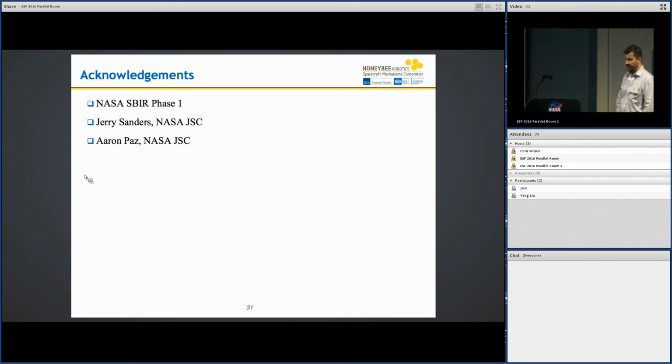Yes, probably yes. The reason why soil is cohesive, the soil that you've seen, is because the particles are really jagged, and actually lunar soil, the old one, has 50% agglutinates, which are even more jagged. So lunar soil has so-called apparent cohesion. The true cohesion is actually due to water here on Earth, where you have surface tension.